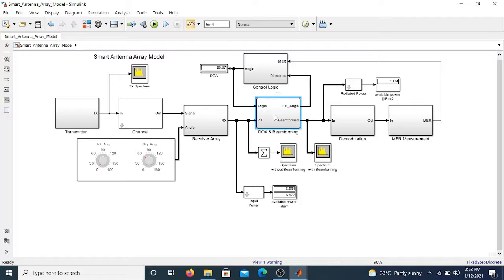So it's only possible to simulate up to 8 antenna elements when you're going to have noise in the system. But if you have more than 8 antenna elements or ports, which are categorized as S parameters in Simulink, then noise will not be simulated in the system, which is not what we want. We want noise to be in the system so that it can be simulated and nullified at the same time, along with the desired signal.